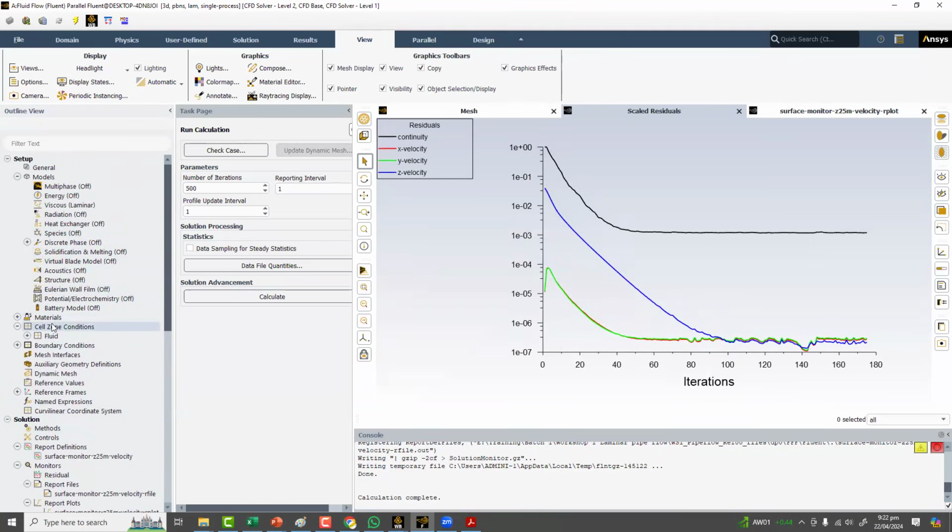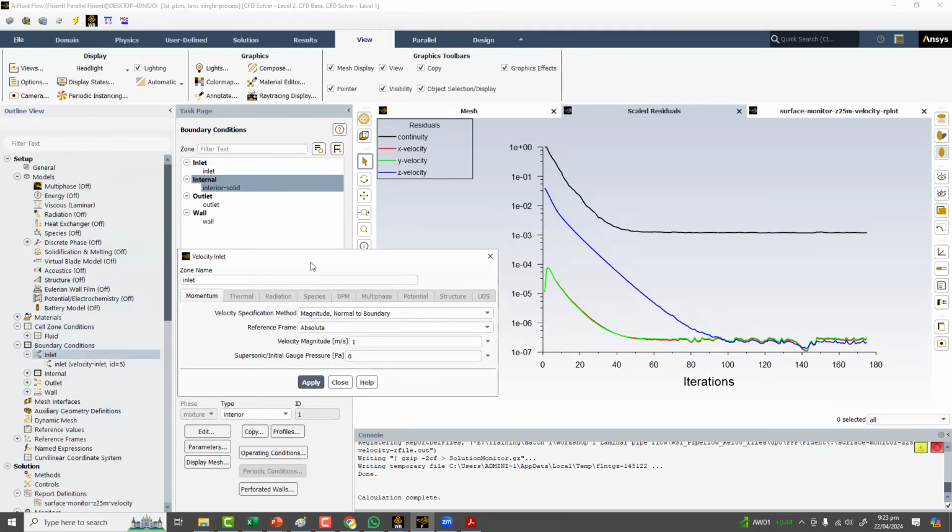See, if you're talking about turbulent flow, in that case those inlet parameters may affect the solution, like the boundary layer. For laminar flow, we don't have those conditions. We don't have the turbulence quantities for laminar flow. But for turbulent flow, we have the turbulent intensity. Turbulent intensity is nothing but a variation of the velocity. Right now in our pipe case, the velocity inlet is 1 meter per second.